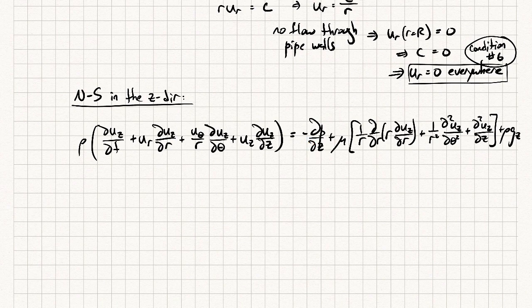The way you can think about that is imagine you have a little piece of fluid and you have a pressure on both sides, but there's a little bit of a pressure difference. So if this is dz, then from the Taylor series approximation, you can see that we have a little bit of a pressure difference potentially from one side to the other. So this is the net pressure. The pressure P's will cancel out, and what you're left with is the net pressure force acting on the fluid, which is just the pressure gradient. So this is the net pressure force acting on a piece of fluid.